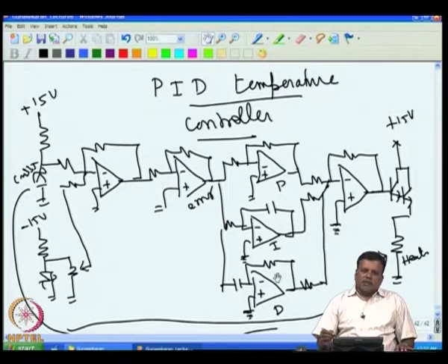That is good, because if I have only one time constant or only one delay in the system, then the maximum phase shift that you can get would be only 90 degrees, because one RC can produce only 90 degrees of phase shift, not more than that. With 90 degrees of phase shift, the system will not oscillate even if the gain is higher, and that is good for us because we do not want the system to oscillate.